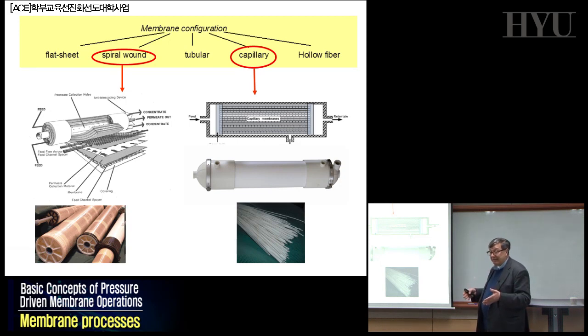It's because we need, for different kinds of separation, hollow fibers or flat sheet. If you are using hollow fibers where it's better to use flat sheet, you are losing 20–30% of your capital investment. You are going to destroy the system. Vice versa, if you are using hollow fiber when it was possible to use flat sheet, you are losing a lot of money because normally hollow fiber has a cost 5 times higher than the flat sheet.